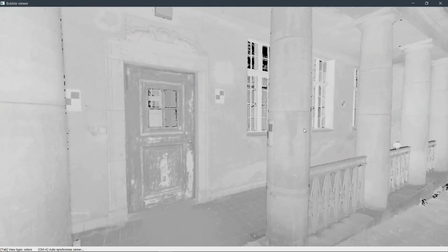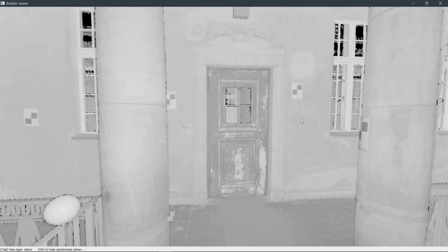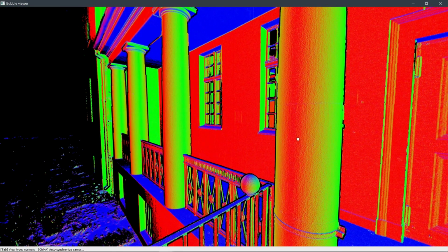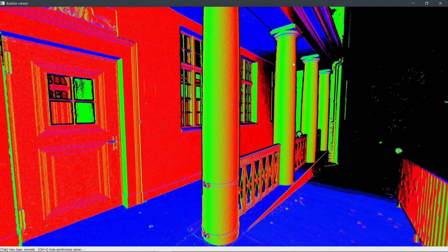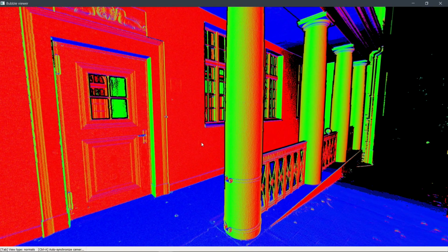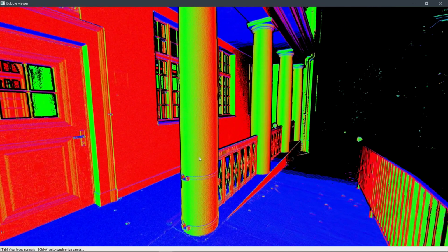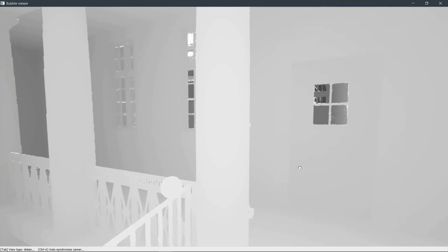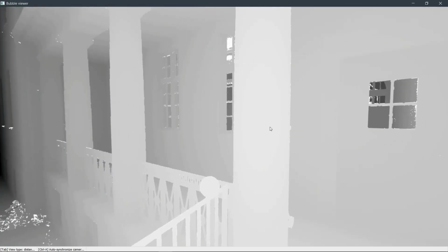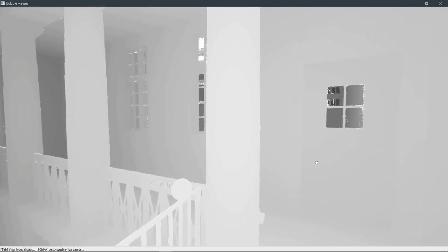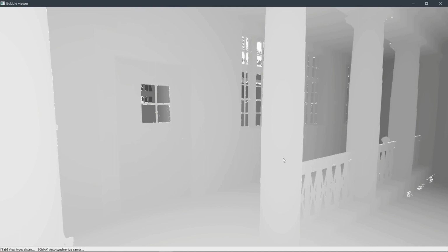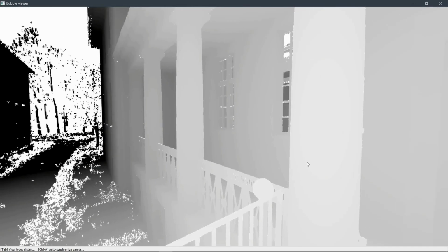Like this you can drag and scroll around the view, and this also has 3 visual representations that you can change with the tab key. So the first one was the RGB colors. Here are the normal vector views. So for example, here it's represented with the UCS colors. So for example, the blue ones here are perpendicular to the Z-axis, and then the green and the red ones represent the X and the Y-axis as well. So the next one is the in-depth visual style with the grayscale, meaning which elements are further away or nearer to the scan position of this image right here.